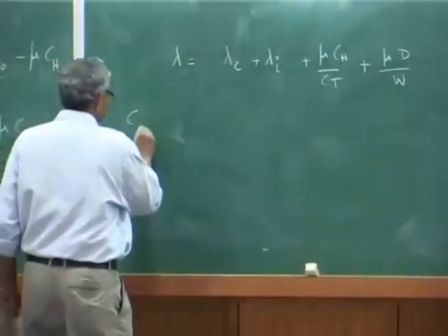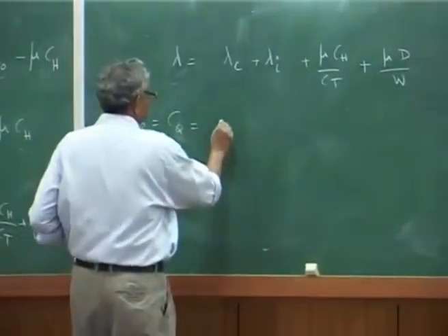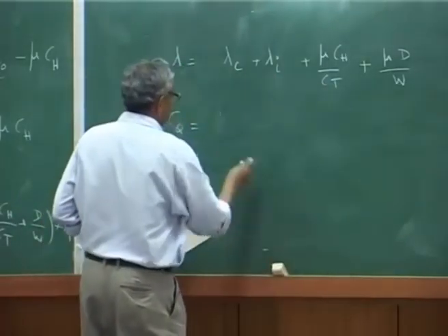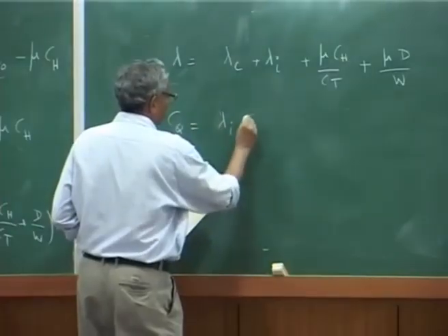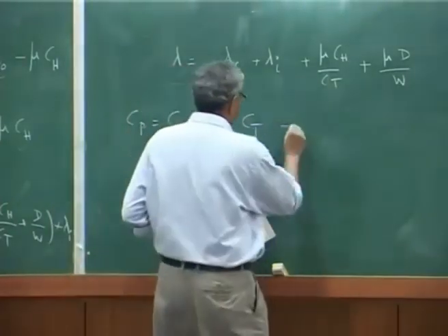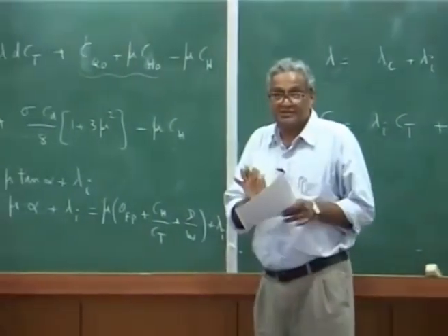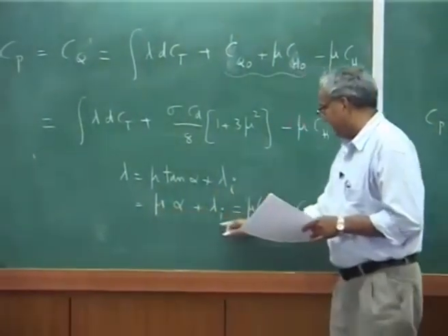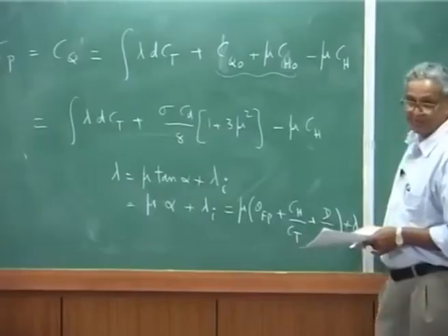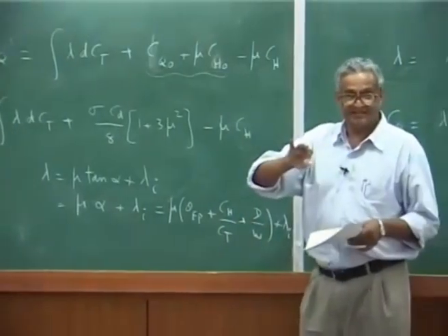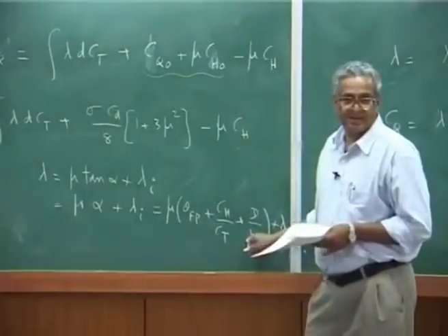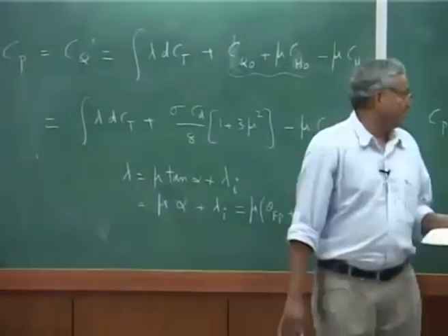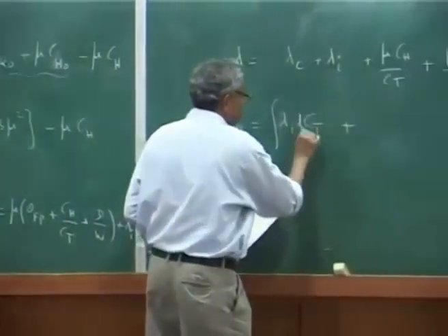So, I will write Cp which is equal to Cq which is equal to lambda Ct, and lambda I am writing all these things. So, I will have lambda I Ct. Climb velocity, suppose if you do not want to do all those things, I do not want to substitute, I will keep climb velocity, because I can substitute for lambda this entire expression. I may say lambda I may be varying, but rest of them are all constant for the vehicle. So, I can directly substitute here, okay. In which case I can put lambda I Ct separately,